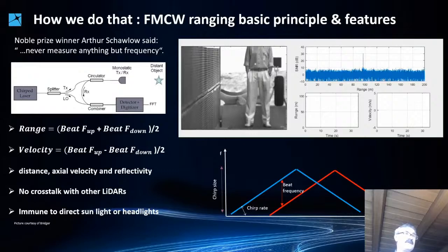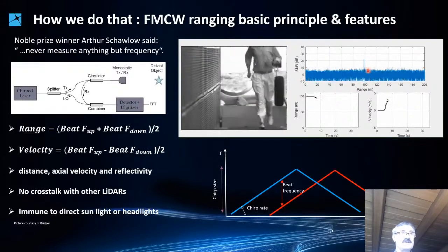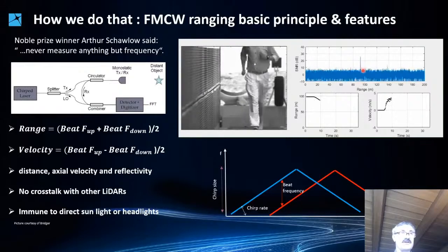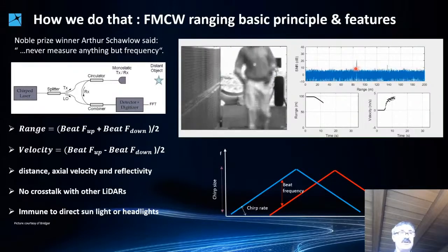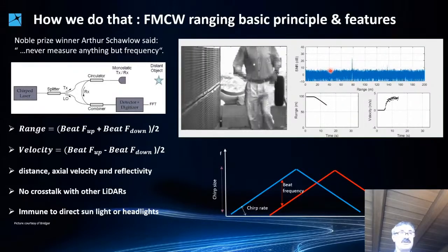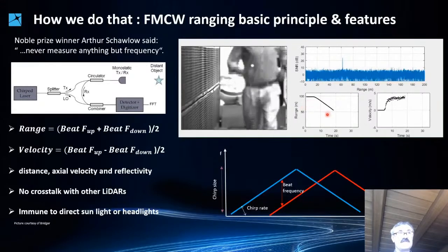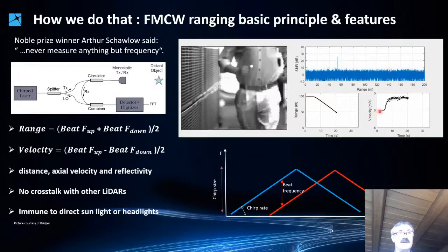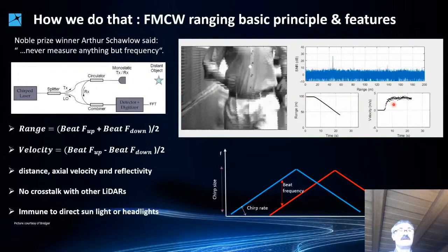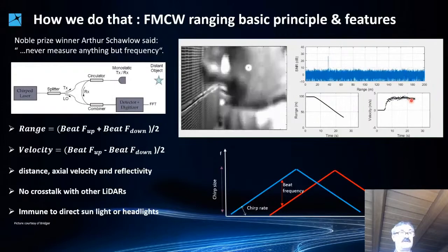I will repeat the demonstration one more time and give you additional explanations on that. This is a spot. This is the object. This is a peak which is detecting the location. Object moves, peak changes the location. So we measure simultaneously the range, which is shortened in this case because the object is moved toward us, and we measure simultaneously the speed of the object.